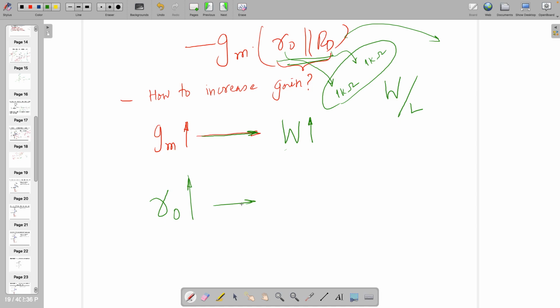Let's go this way. Then understand, L you have to increase, but note that in our course we can touch L. In other places like digital, they do not touch L at all. If you are studying another course like digital MOS LSI, do not touch L anywhere. L has to be the smallest one to achieve the highest bandwidth.